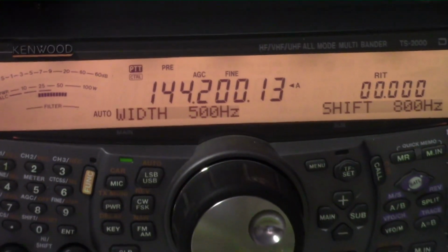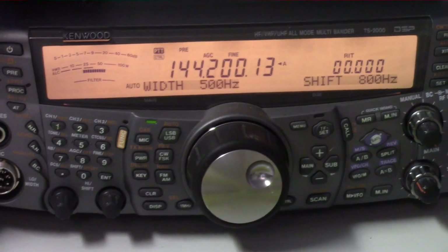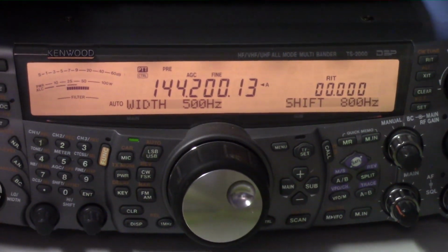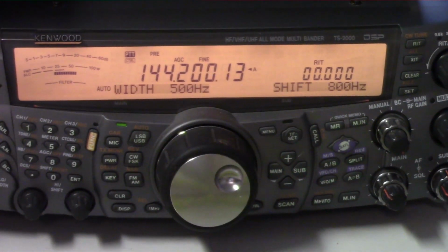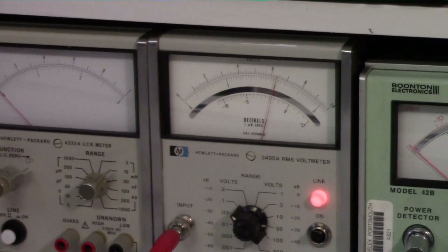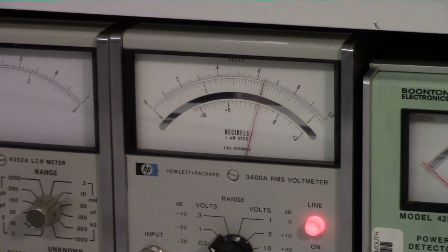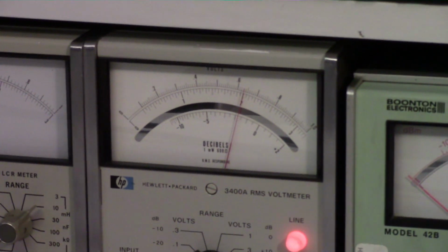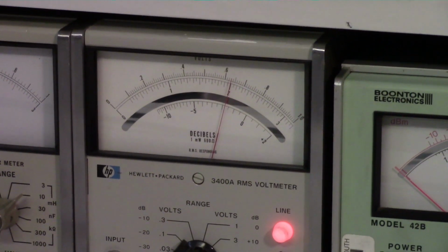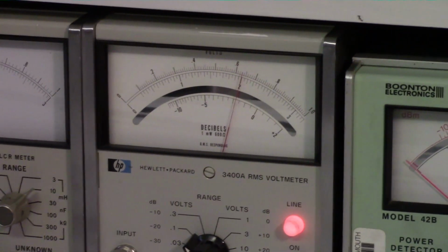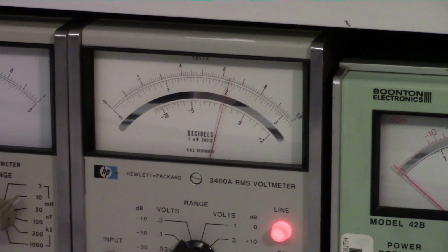But every real filter, with the exception of software-defined filters, well, even they have some small ripple, but real mechanical filters and things like that will have a small amount of ripple, and you'll find that as you tune across the passband, the amplitude will go up and down, just as we saw there. So we went ahead and found the frequency. We tuned the radio to where we got the maximum response from that carrier.